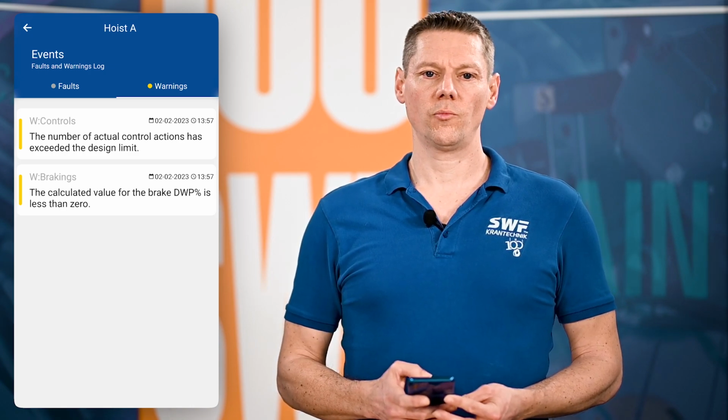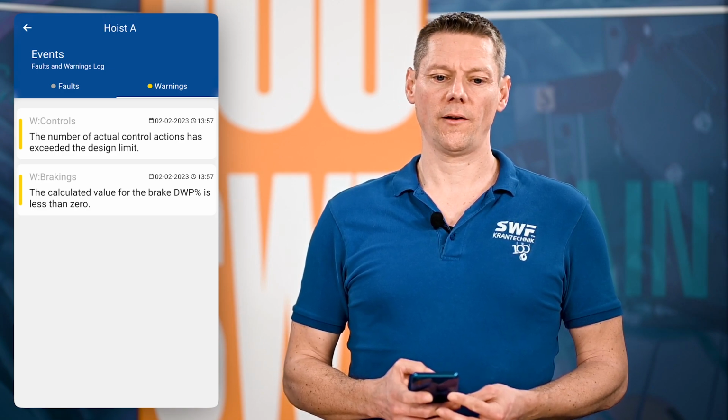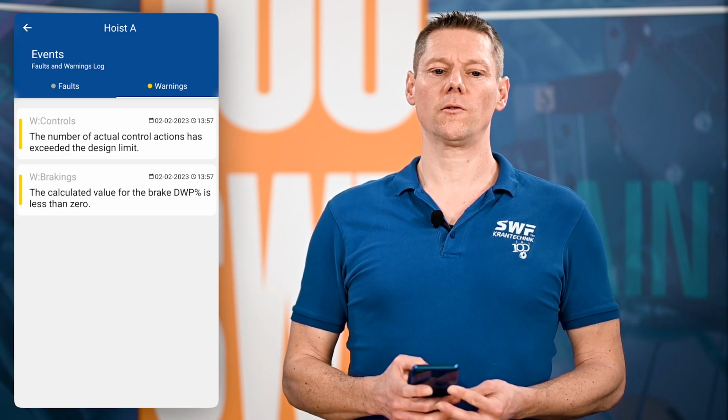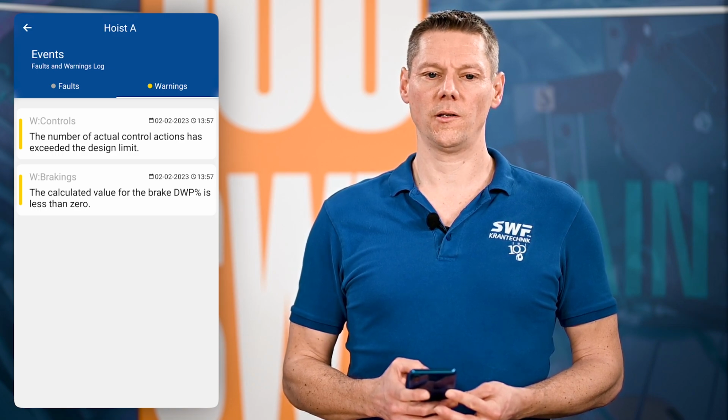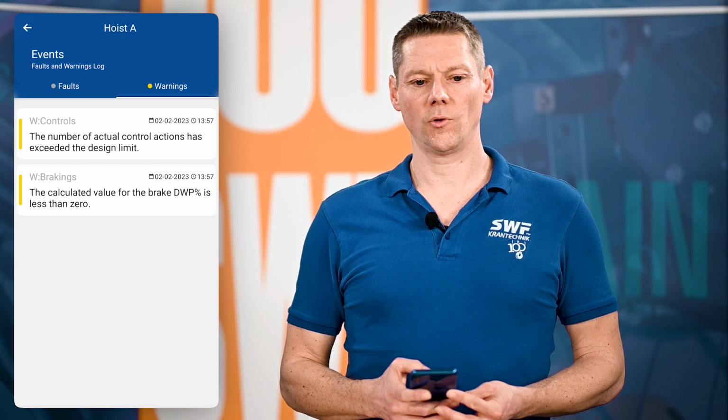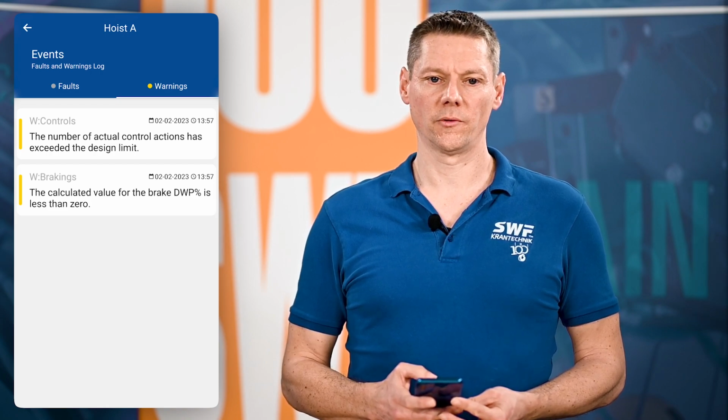The brake warning means that the hoist brake needs to be replaced, and after we have replaced the brake and the contactors, we need to reset parameters in the OMNI control, and then this will also reset the warning information here in the app. If the OMNI control detects an active alarm, we can check this active alarm also here in the app. An active alarm is a bit different from a fault, so there is no damage at the hoist. The hoist is, for example, overloaded because of the operator. The operator maybe tried to lift a too high load, and if the operator lowers the load back to the ground, then the active alarm is gone.